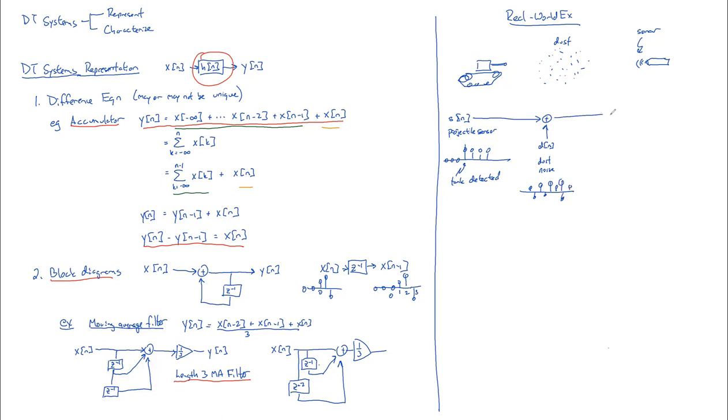And so you're going to take that received signal, and you're going to sample it quickly. You can sample it very quickly because these dust motes are very small. You go through them very quickly. Here's an example of a 4, 1, 2, 3, 4 moving average filter. So divide it by 4. And here's your processed signal p of n.